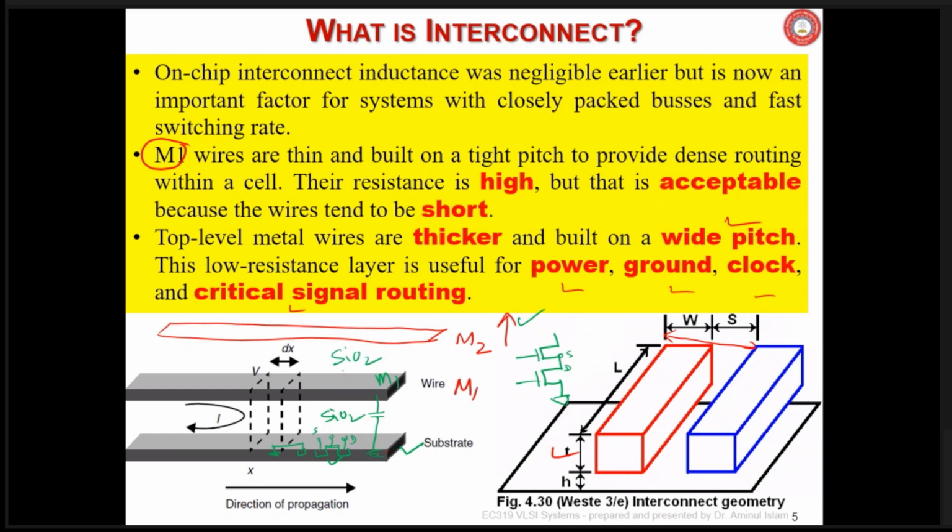Since one big processor needs billions of transistors, if you try to connect with only one metal layer, like you can see in a printed circuit board of radio, television, etc., where only one copper metal line connects different components in the PCB, possibly it will take a very big area. Say around 40 billion transistors are there. If you want to connect all those with only one metal layer, it is going to take huge chip area. That is not possible, because within a small silicon area you have to make big circuits.